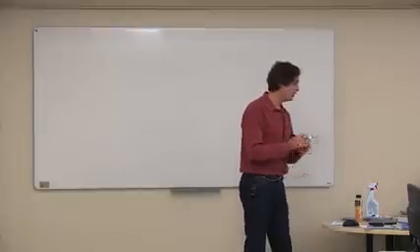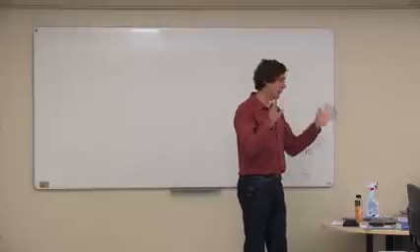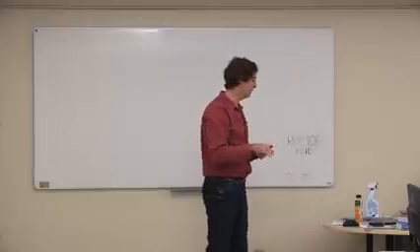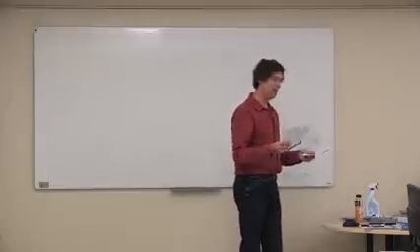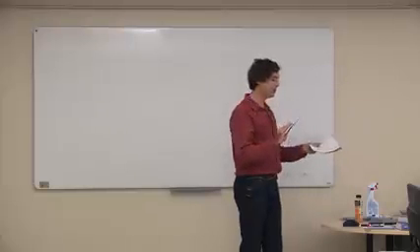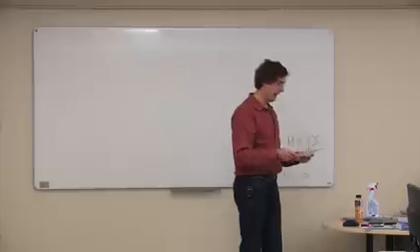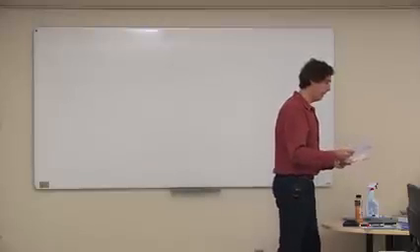So the next step after that is to think, well, we've got a certain number of pieces of equipment that we want to put on the P&ID, so we need to organize it a little bit. This morning I got up, thought it through, and threw together a couple of rough sketches of P&IDs, mostly thinking about where I want to put the equipment on the piece of paper. I think I was fighting with myself as to whether I want to put the steam drum on the left-hand side or the right-hand side of the reactor, and it probably doesn't make much difference in the end.